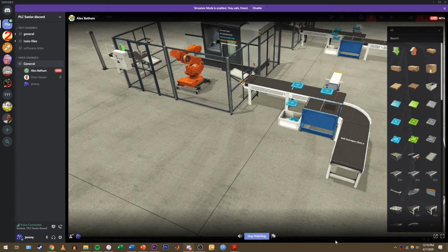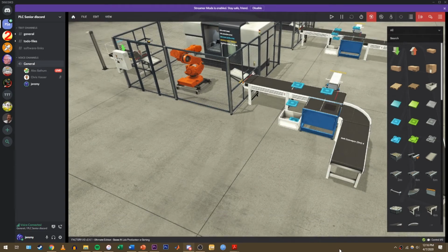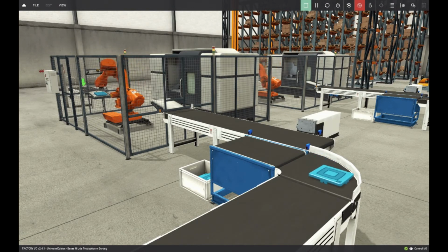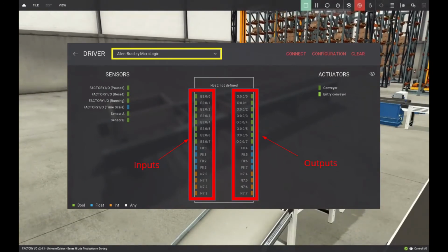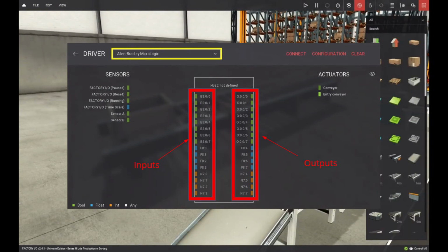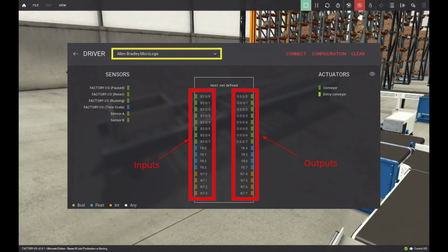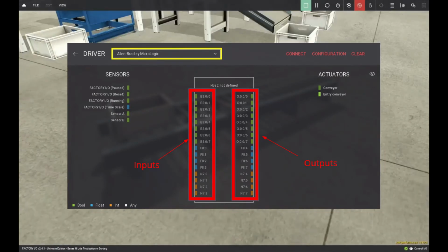Testing the PLC using the first method may take a long time to set up, and using the second method may be difficult to monitor all at once. So combining something in between these two options may be the best option. Switching the parts associated with each input and output in Factory I/O is very easy to do and can be done by simply dragging and dropping the desired part to the desired I/O.